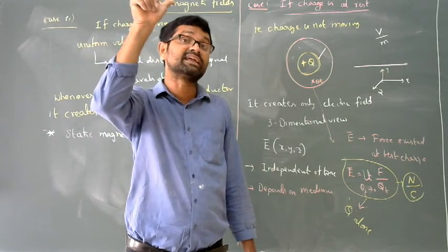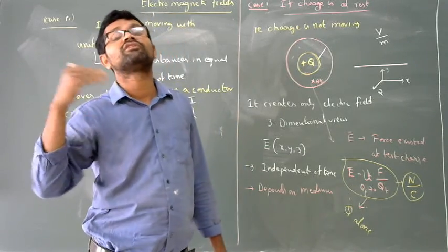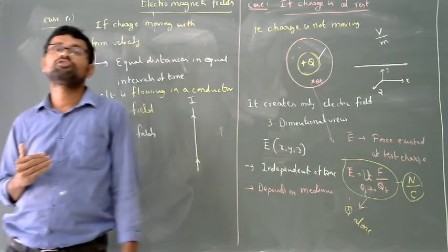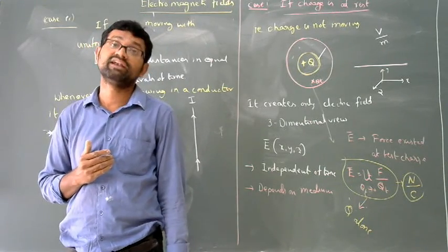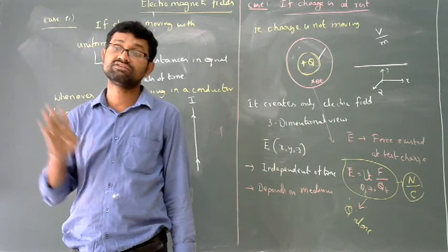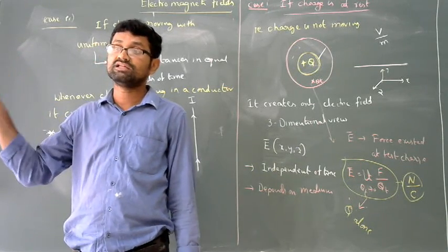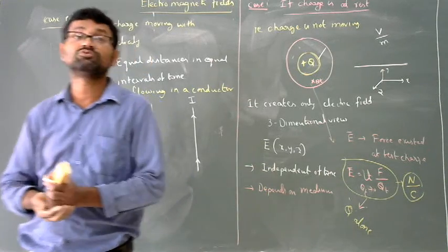For a straight current carrying conductor, we represent current direction with the thumb. Then the remaining four fingers represent flux directions. Similarly, for a concentric winding, a continuous winding, the current direction we represent with the forefinger. Then the thumb indicates north pole polarity. The bottom one indicates the south pole polarity.